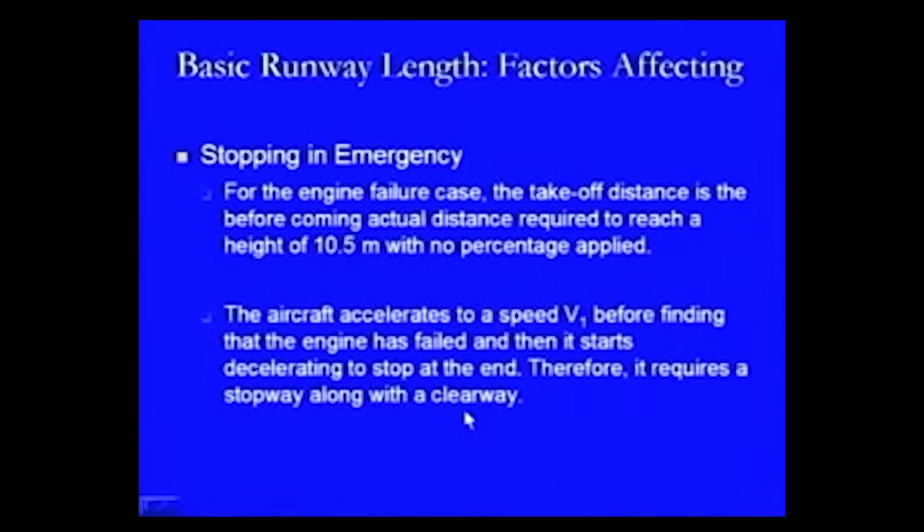Then the other condition is stopping in emergency. What happens in this case is that there may be an engine failure, and in this engine failure case the takeoff distance is the actual distance required to reach a height of 10.5 meters, with no percentage applied. The aircraft is trying to attain speed, which means it is accelerating.